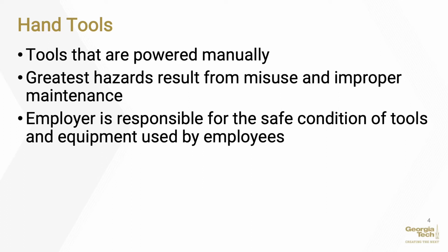Employers shall not issue or permit the use of unsafe hand tools. Employees should be trained in the proper use and handling of tools and equipment. Employees, when using saw blades, knives, or other tools, should direct the tools away from aisle areas and away from other employees working in close proximity. Knives and scissors must be sharp. Dull tools can cause more hazards than sharp ones.